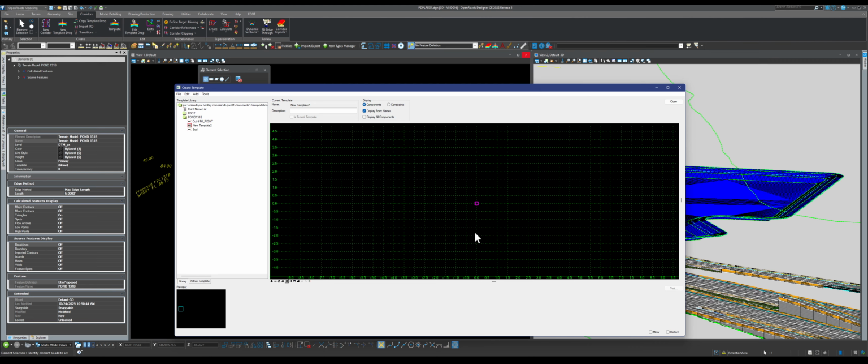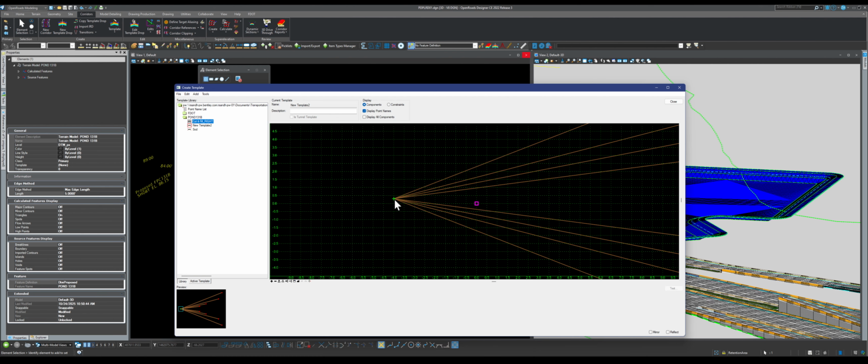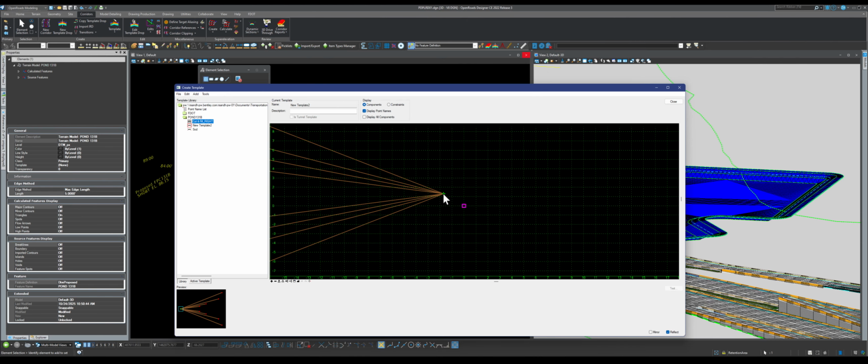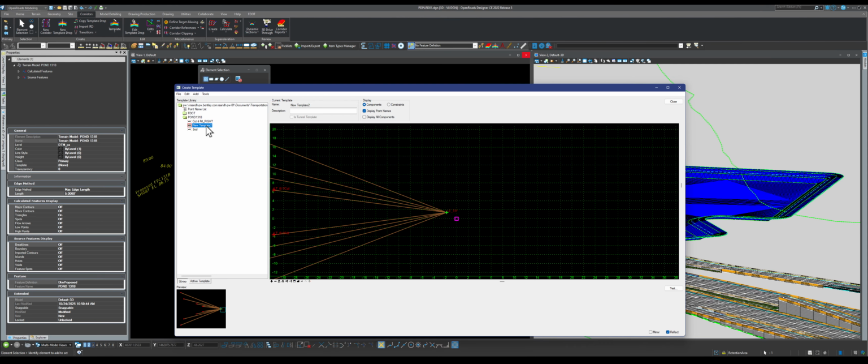But I'm not going to draw everything from scratch. What I'm going to do is, you can come here and drag it. But while you're dragging it, you see it's still right, but I want it to be left. So while you are holding the left button, right click too, you're going to get this menu. This menu will give you reflect. So if I did reflect, ta-da, now I reflected it. And just drop it here. Here we go. So now you got your reflect. So let me just copy this name, because I'm lazy, and put it here. And then let's call this left, L-E-F-T.